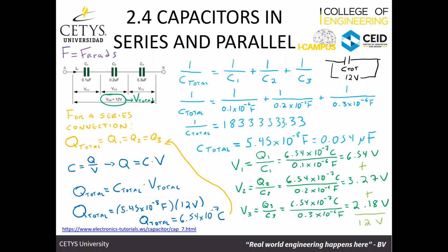First, we talked about the concept of the total or equivalent capacitance. I have three capacitors here. Instead of three capacitors with three individual values, if I were to substitute one capacitor that would have the same effect, what would that value be? That's called the total or equivalent capacitance. For a series array, it's the reciprocal of the sum of the reciprocals.